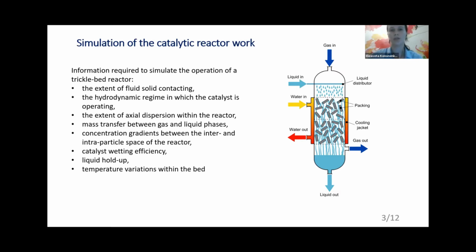The simplest and most common type of heterogeneous reactor is a trickle-bed reactor. This type of reactor is a chemical reactor that uses the flow of liquid or gas up or down under the action of gravity or pressure through a packed layer of catalyst pellets. Although the principle of operation of the reactor is simple, optimizing the operation of such reactors is still an actual task, because heterogeneous catalytic processes are a complex combination of many separate processes such as mass and heat transfer, in addition to the chemical conversion of reactants into various products and byproducts of the reaction.